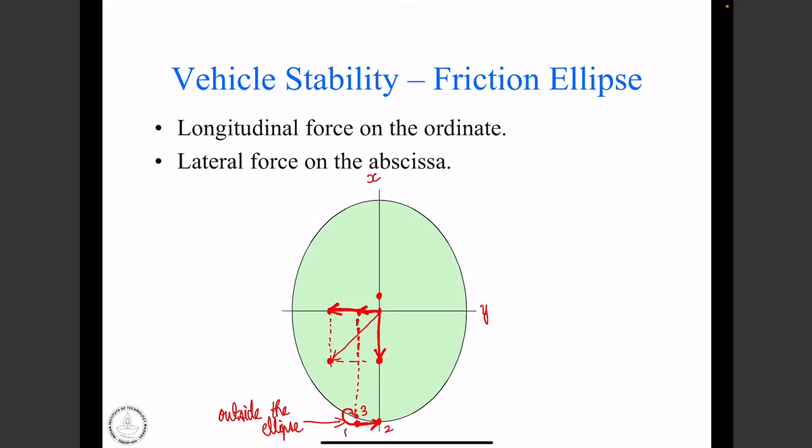So the ABS system will reduce the brake pressure so that the braking force is maintained within what is available at the tire road interface.